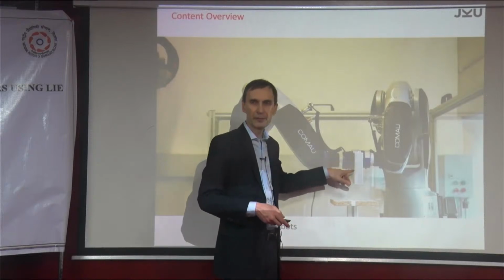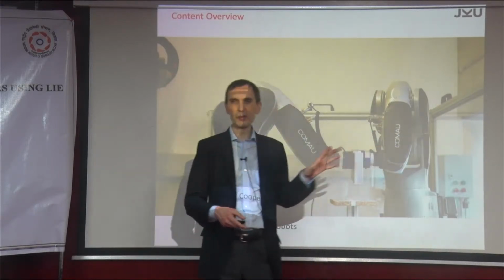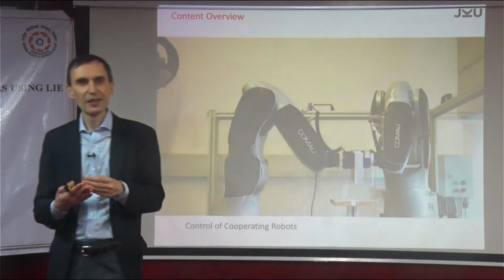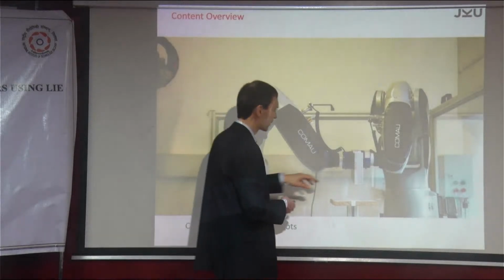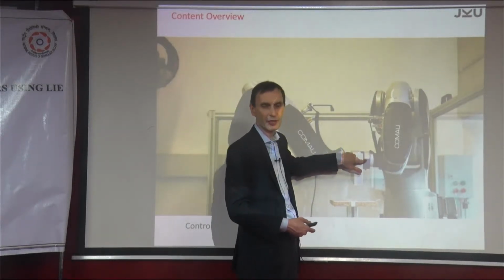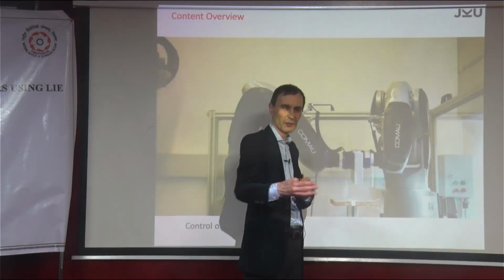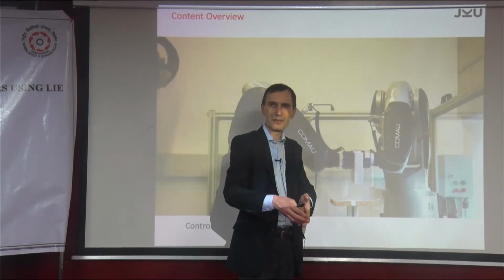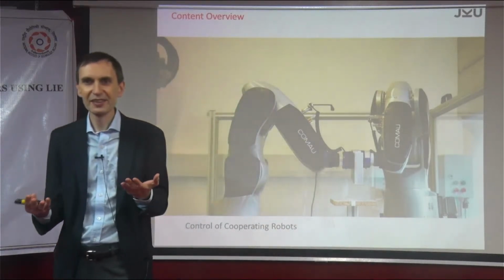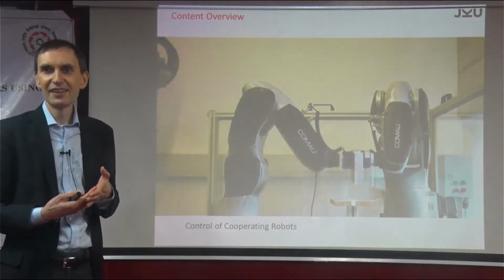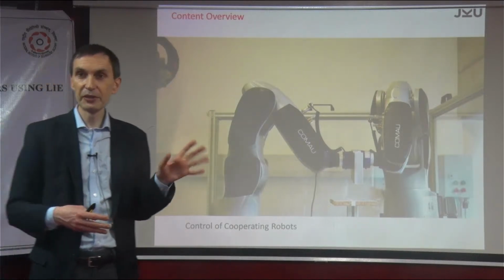So what's the problem here? What are the limitations of an industrial robot? For example, what's the accuracy? How precisely can you position the end effector? The end effector is the flange here. If you control a robot, what is the position accuracy with which you can reach a point? Is it a millimeter? Is it a tenth of a millimeter? If you just buy it off the shelf, it could be in the millimeter range.